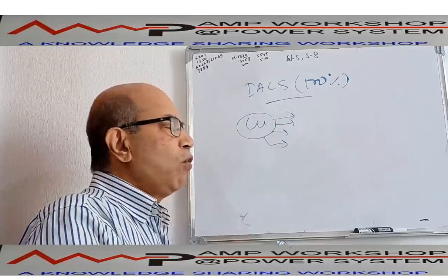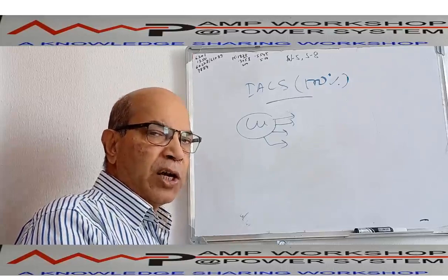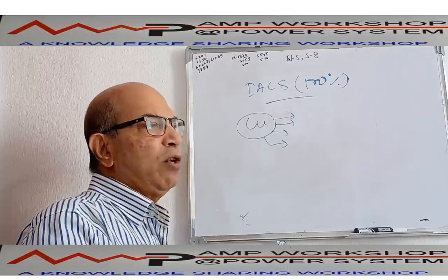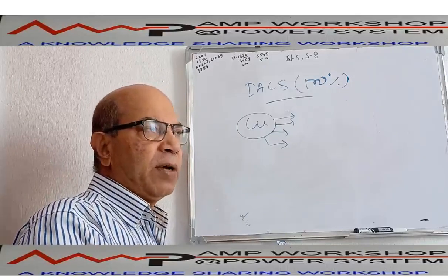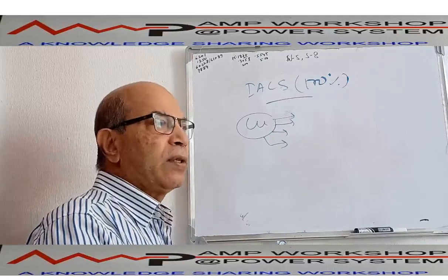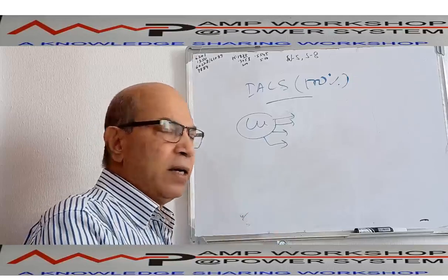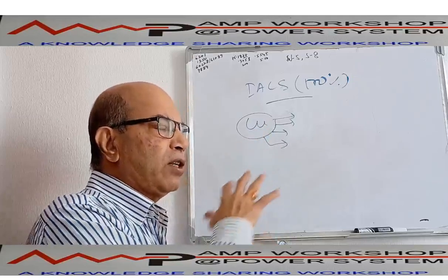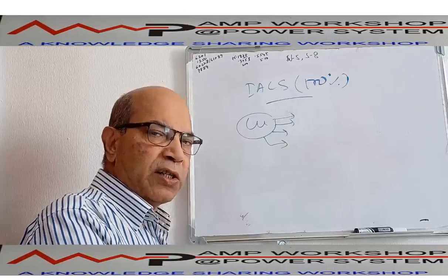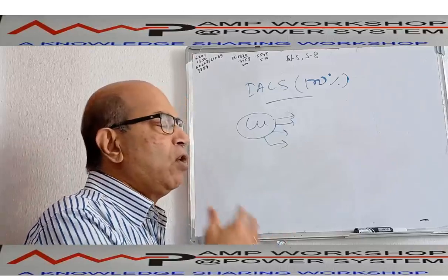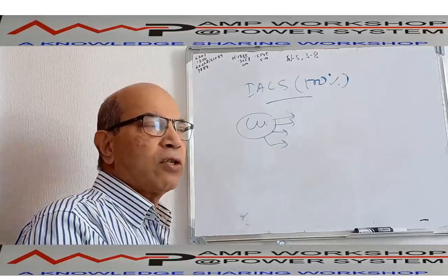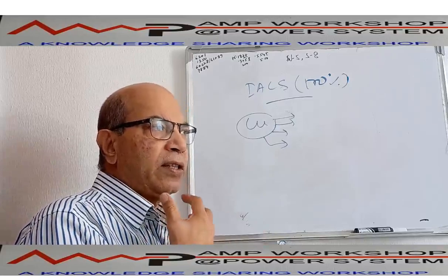Considering all these things, copper is not the preferred conductor for the overhead transmission system, except in some cases like the overhead train lines or tram lines, where the solid conductor is required to move with the pedal. In that case, we use copper wire. Otherwise, for normal electricity transmission and distribution, either low voltage or high voltage, we do not use copper, because copper is expensive and it can get stolen easily.